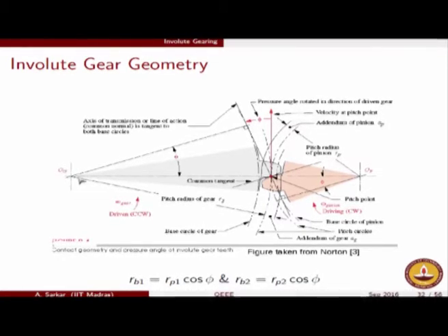Since the gear is attached to the shaft, which you can assume to be a beam of circular cross section, this horizontal component passing through the gear center or the shaft center is like a transverse load onto the shaft.